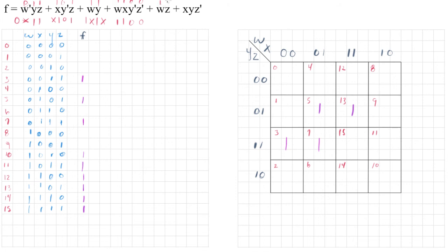Next one, we have both ones, both on. W, no X, no Y, and Z is on. So that's 1, don't care, 1. So we're looking for all the possibilities with 1 at each end. So here's 1, 1, 0, 0, 1. Again, we have the 1s at the end here. We don't care about the center. We don't care about these two bits here. And then all the others with the 1s at the end are already marked. So we're just going to move on to the next one.